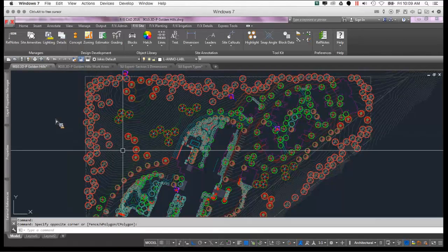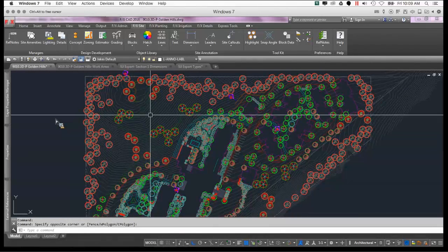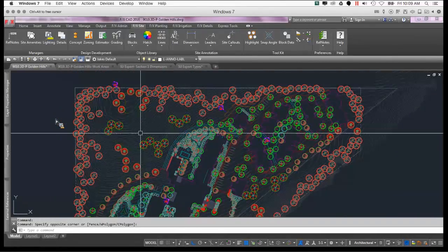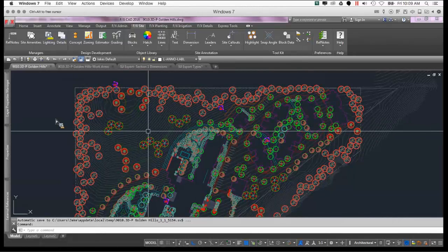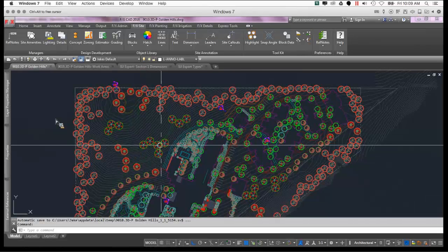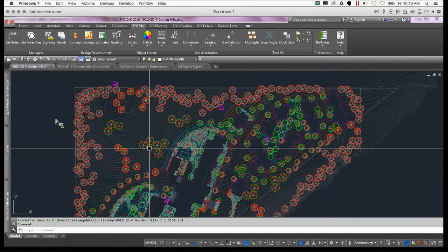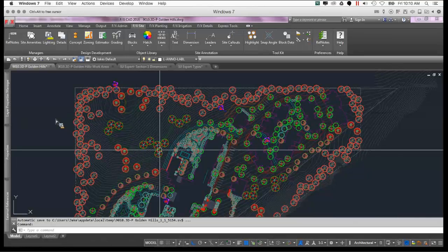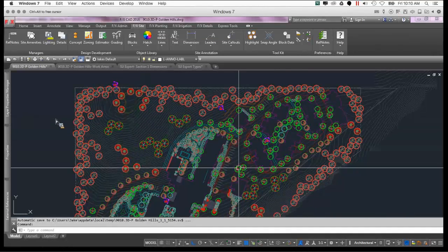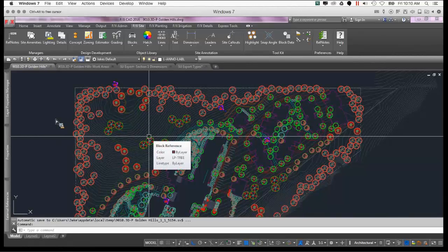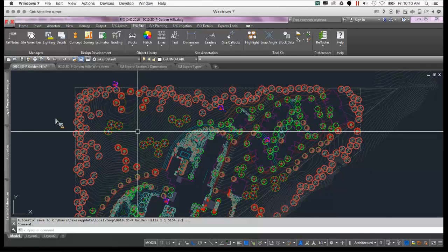The best way to do that is through getting your topography and having those survey points or whatever is going to be your actual base here to be able to generate that proper terrain. Because if we have that information, we can throw it into SketchUp and generate really, really quickly an accurate terrain, to the topography obviously, for you to then slice through to see what it is you're working with. A lot of times it is very hard to see what it looks like in an elevation because it's a flat 2D plan. So bringing it into 3D gives you that sense of space and how it's really going to affect the drawing.